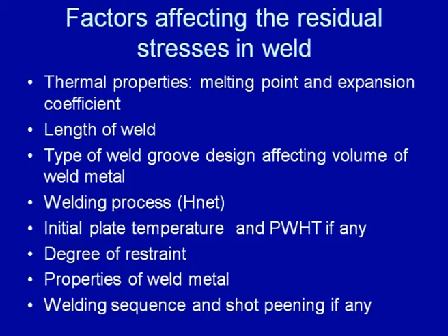The type of the weld group design also affects the residual stress, because it directly decides the volume of the weld metal to be deposited for developing the weld joint. And in general, we know that the greater the volume of metal to be deposited for developing a weld joint, the greater will be the magnitude of the residual stress that will be developed.